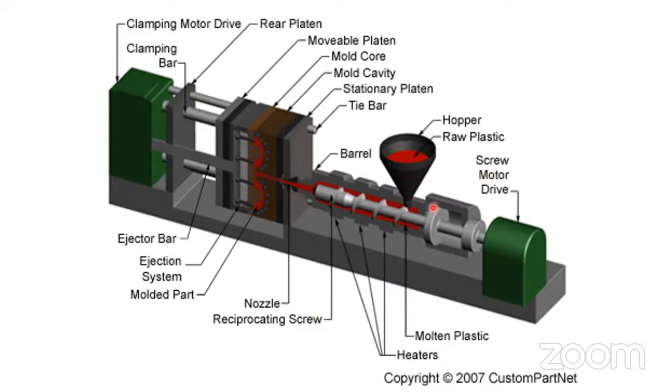I told you the throat of the hopper is a chilled one because a water circulation pipe is going on here. Keep in mind, before starting the machine, you have to supply chilled water around the throat of the hopper.